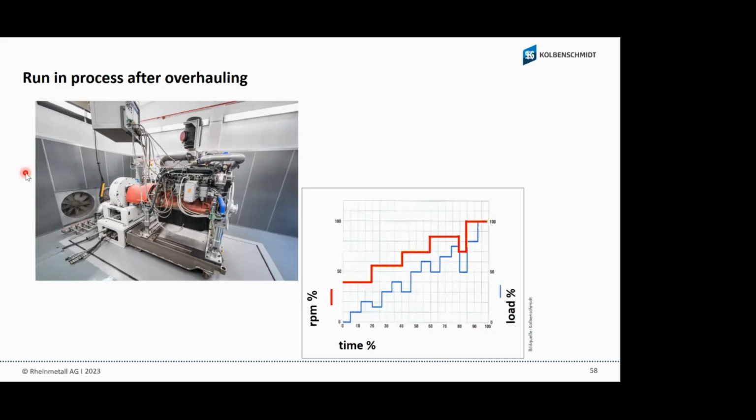No, this is also not good, because exactly in this situation, when you don't have load on the engine, we have two effects. The first effect is that all these components, the surface of the bore, the piston ring, the piston, must marry together. And this marrying together will be quicker when you have much more load on it. And then they have a perfect sealing condition, especially the piston rings. When they have the pressure behind them, they move around in the piston ring groove, and then they will seal the combustion chamber perfectly from the bottom of the oil pan.